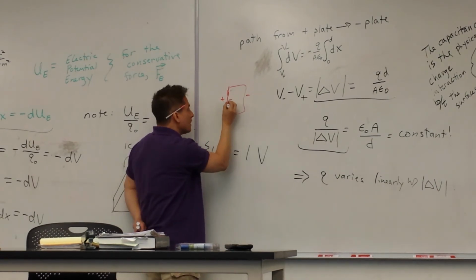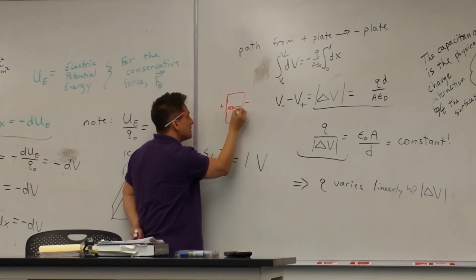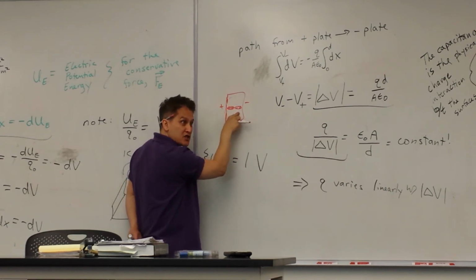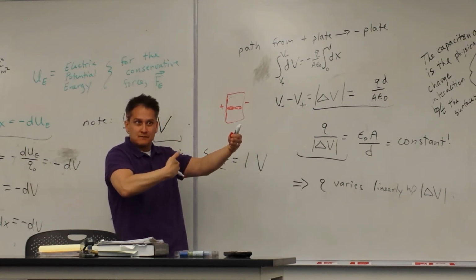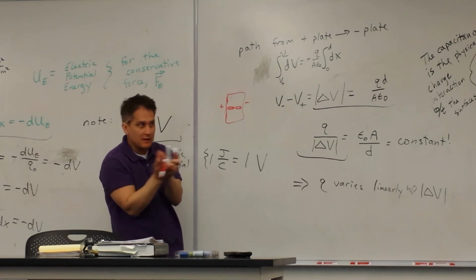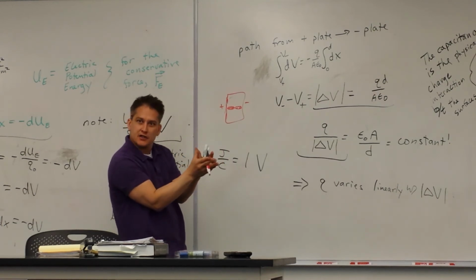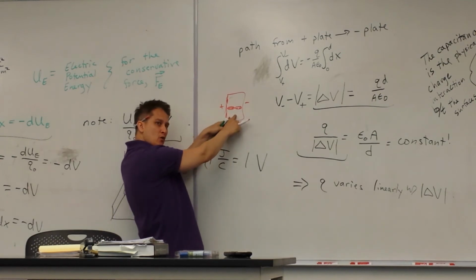So the individual molecules, minus plus, align themselves based on their mutual attraction and repulsion to the charges on either side. So why does the capacitance property, this Q over V relationship, vary when you put something other than air in between? It's because when you have air or vacuum, there's nothing to induce.